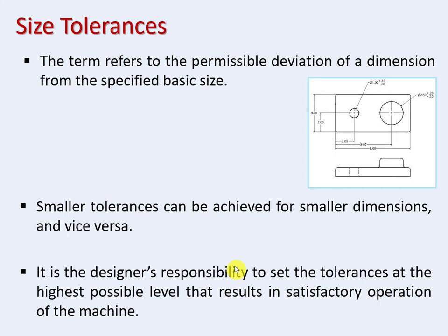It's the designer's responsibility to set the tolerances at the highest possible level that results in satisfactory operation of the machine. So your mission as a designer is to put the tolerance as large as possible to give the manufacturer flexibility to make the part.